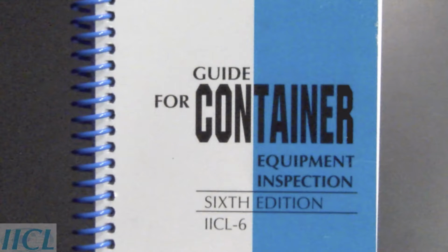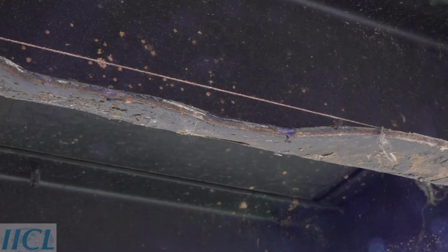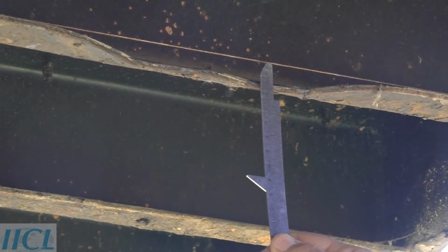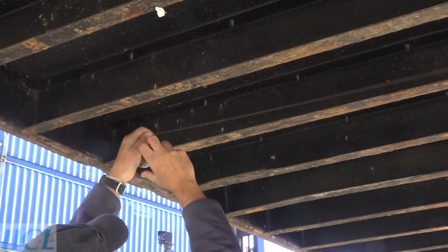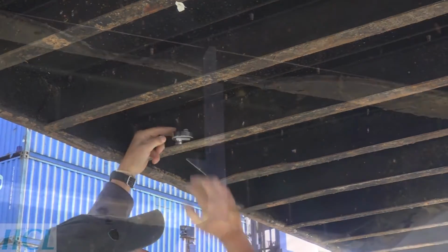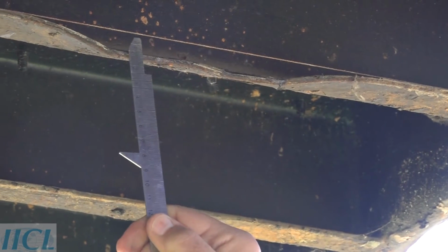In addition to the 50 mm maximum allowable flange damage criterion, the IICL does not allow any part of the crossmember, including the lower flange, to go downward more than 15 mm from its original position. The string line is placed on the upper surface of the lower flange at the flange outer edge. The measurement is made downward to the upper surface of the lower flange at the point of greatest downward deflection.